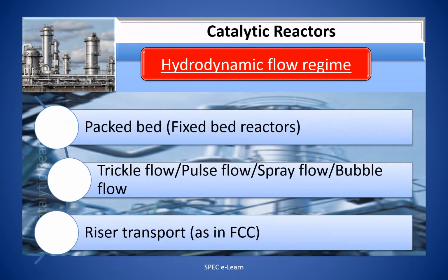Another strategy to be determined during the design stage is the hydrodynamic flow regime for operation. The hydrodynamic flow regimes include packed bed or fixed bed reactors, trickle flow or pulse flow or spray flow or bubble flow, and riser transport as in the case of FCC.